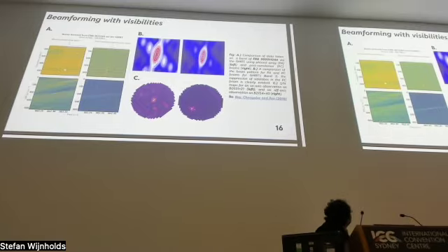And here in one of the FRB observations, this is a normal phased array beam, and this is a post correlation beam. Here it can be clearly seen that the effects of RFI compared to this one are very much reduced. And also you can see the baseline is much more stable in this post correlation beam, because in post correlation beamforming you are actually getting rid of the self term of these antennas, which causes such baseline variations.